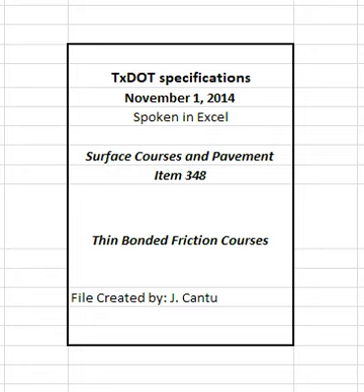4.3.3 Production. For production, include loader operation procedures to avoid contamination in cold bins. Procedures for calibrating and controlling cold feeds. Procedures to eliminate debris or oversized material. Procedures for adding and verifying rates of each applicable mixture component, for example aggregate, asphalt binder, RAP, RAS, lime, liquid anti-strip, WMA, fibers.